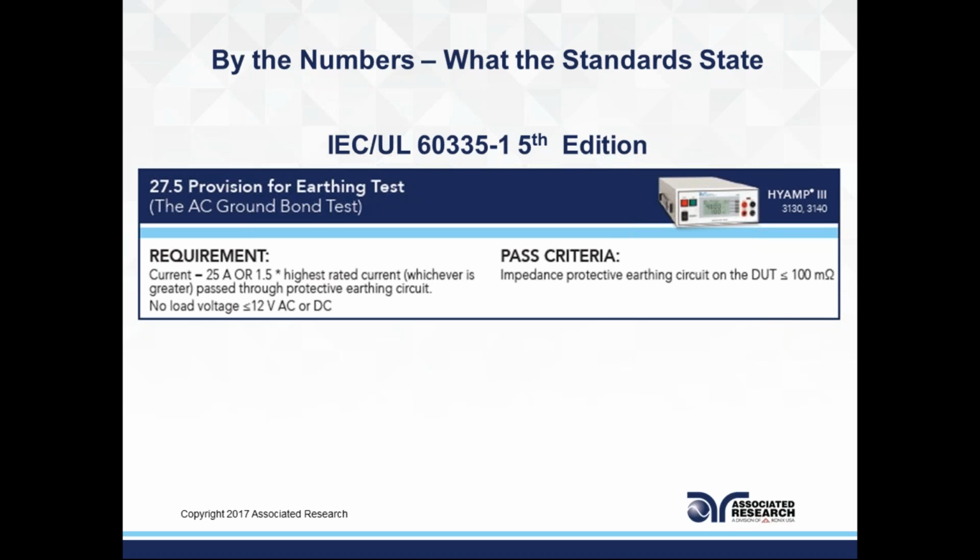You can set a voltage high limit and a voltage low limit, which allows you to not do the conversion outside of the instrument. The instrument does the calculation for you. Basically, we're using the same formula, Ohm's law, V equals IR. We are already measuring the voltage, but the resistance is displayed as a calculation.